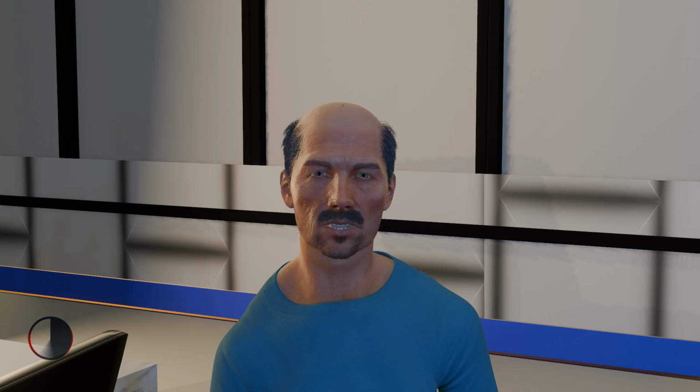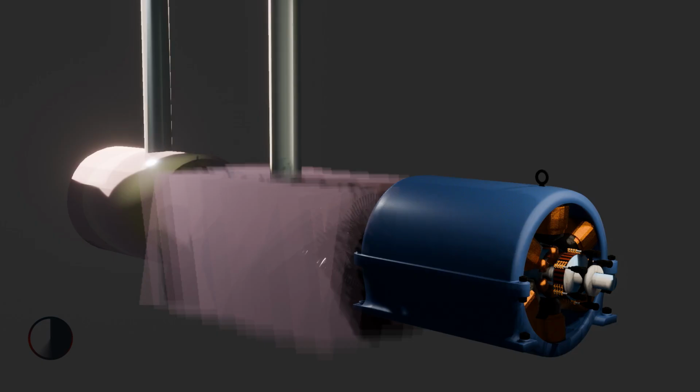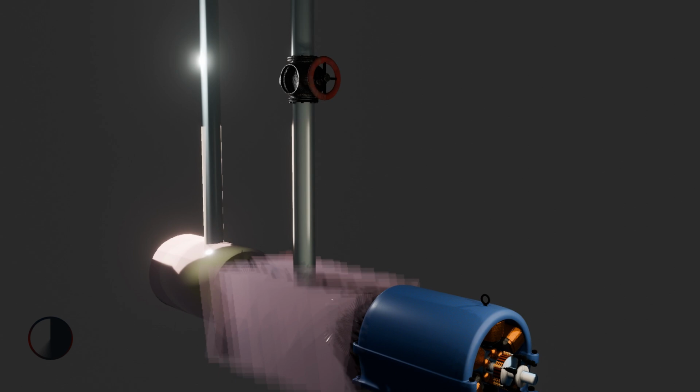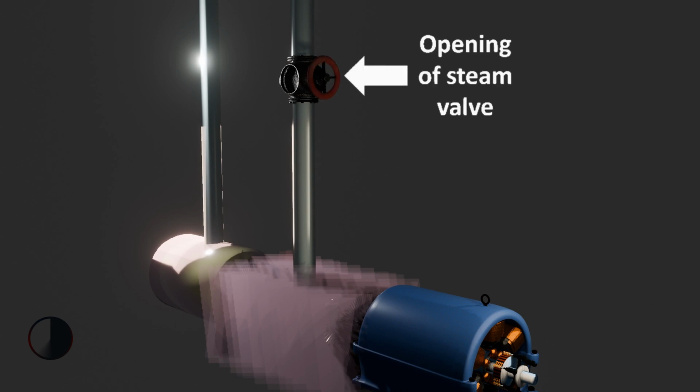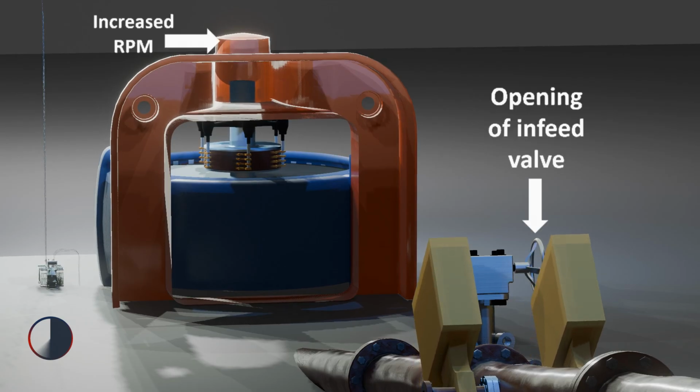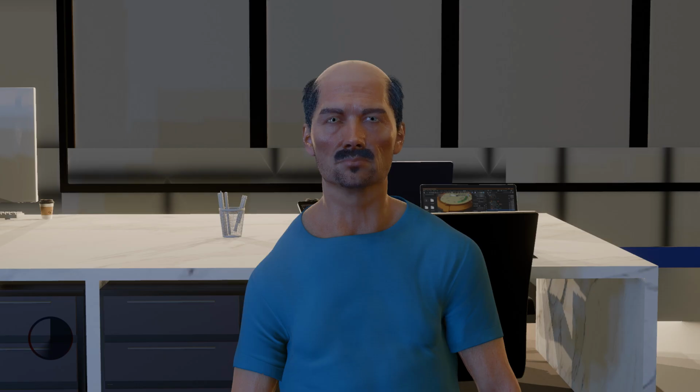When the frequency is not up to the required value needed before synchronization, the generator is brought up to approximate synchronous speed by supplying more energy to its shaft. For example, opening the valves on a steam turbine, opening the gates on a hydraulic turbine, or increasing the fuel rack setting on a diesel engine.